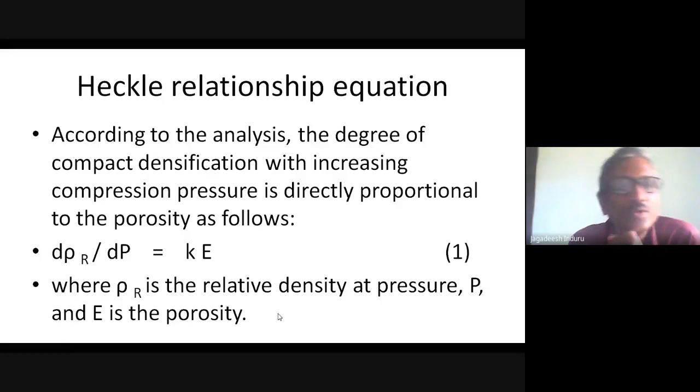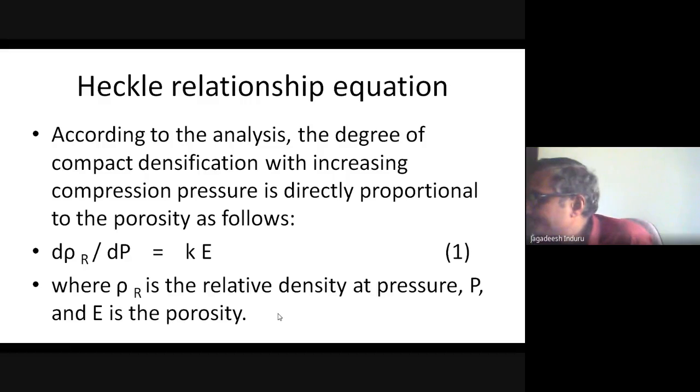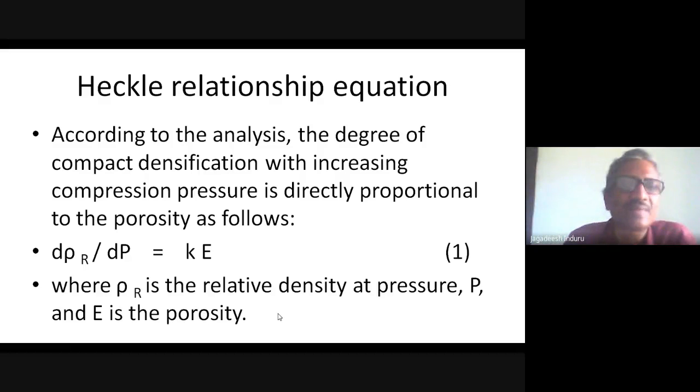So you take the duff mass and you convert it into wet mass. When the wet mass is getting compressed and passed through the sieve, you will get wet granules. After the wet granules are there, you are going to dry them and get dry granules. These dry granules are converted into a tablet by compression.